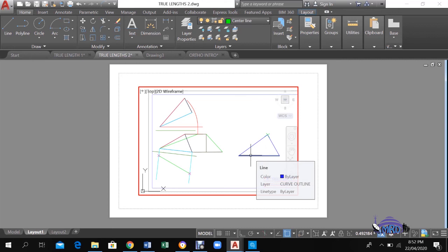Please note that this is orthographic projection, and as such, you must label your views, you must label your true lengths, you must label your true shape. So marks will be awarded for all of those things. Also then, if you are questioned on true lengths, true shapes in a multiple choice exam, or if you have an exam where you're asked to draw these, then there should be no major problem.